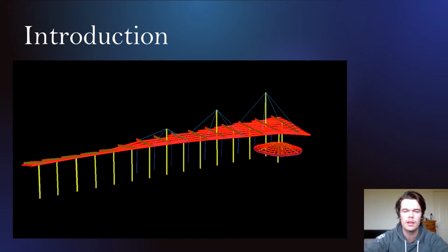and elements. The finite element software will determine the displacement of each node and use these displacement results to compute the stress and strain occurring by assembling each equation into a global problem equation. The more elements in the finite element mesh, the more accurate the approximate solution will be. The linear static structural analysis conducted in this design check assumes a linear relationship between force and displacement vectors.